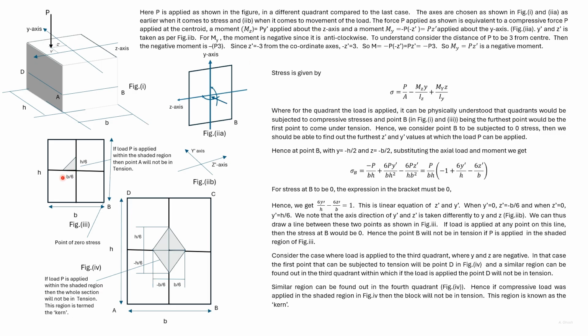So within this quadrant, we have now found an area where if P is applied, the stresses in the section will be compressive.